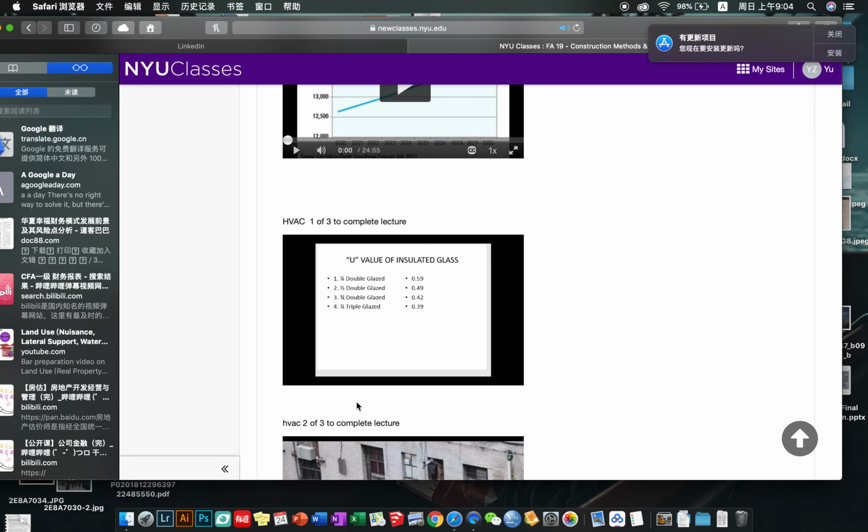Right? But when you look at the comparison between number 3 and 4, double glazed glass versus triple glazed glass that's much thinner, it's the triple glazed glass that actually has the better insulating capabilities and the ability to prevent heat transfer. So glazing has a higher effect than the thickness of the glass, but both do contribute to helping insulate it. So it makes sense, right? A thicker barrier with more layers of protection will always be a better insulator than the thinner barrier with less layers of glazing protection. Okay.